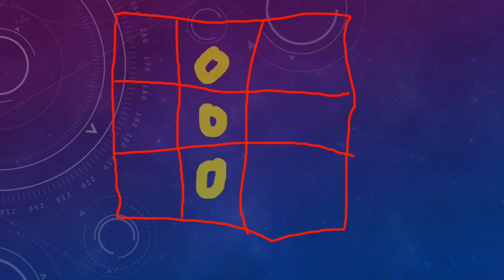But I will tell you one practical thing, then you can decide why the minimum distance is not always possible. For example, you know that there are two types of ceiling, tile ceiling and gypsum ceiling. So we have a tile ceiling like this. Here in the center of this room, I install the sprinkler following the NFPA 13 requirement, minimum and maximum distance rules. And at the two ends, I have given importance to the lighting, which is of prime importance for the room because lighting is the appearance. And we have four tiles left, 1, 2, 3, 4 in the corner and 2 nearby.